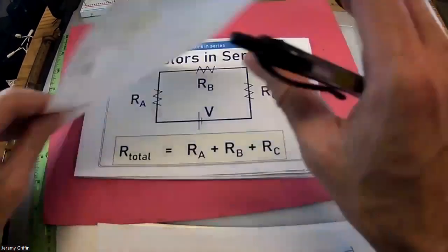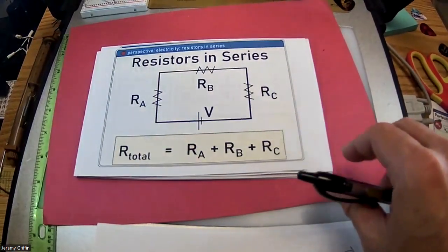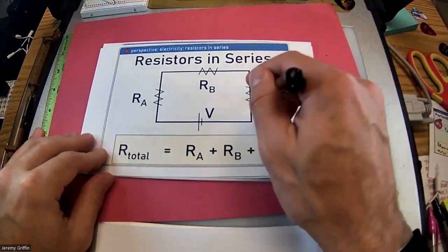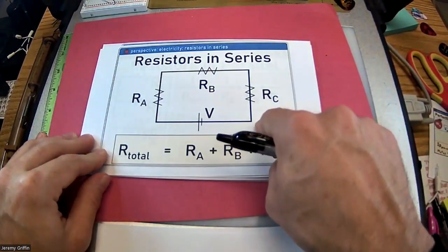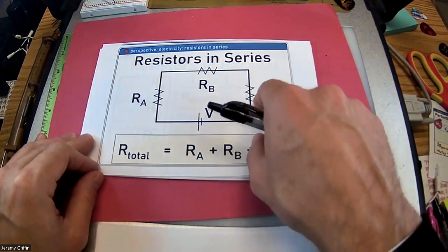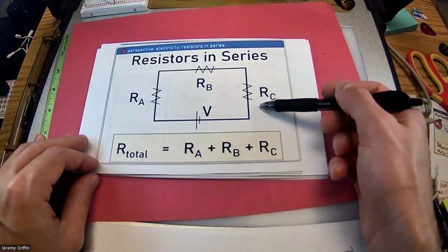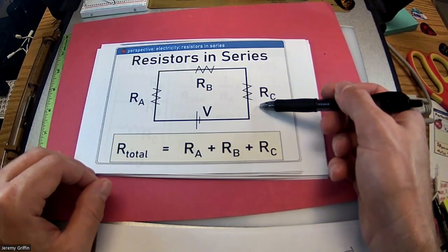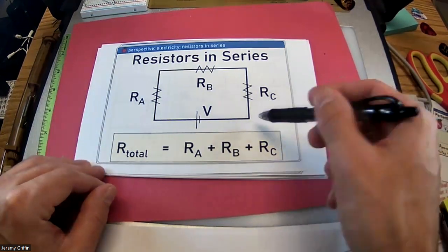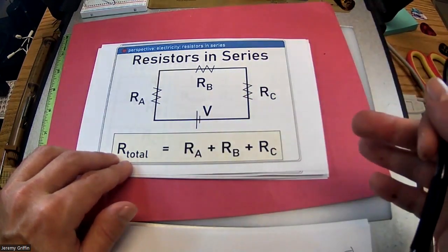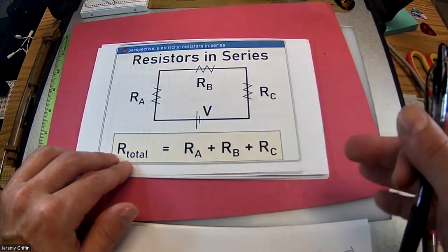Right? Flashlight. I showed you guys a few Paul Hewitt demos yesterday, and at the end he started wiring light bulbs across a car battery, 12-volt car battery, different ways. The first thing he did was he put them all in series, like one after another. And every time he added another one in series, what happened to the brightness of each bulb? Yeah, it got dimmer and dimmer, right? Now, from the point of view of the battery, it was as if the resistance was going up, up, up, up, up. So it was pumping out less and less current. That would be hand in hand with Ohm's law.